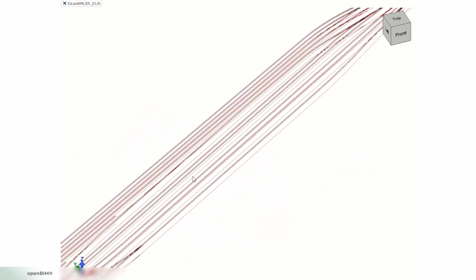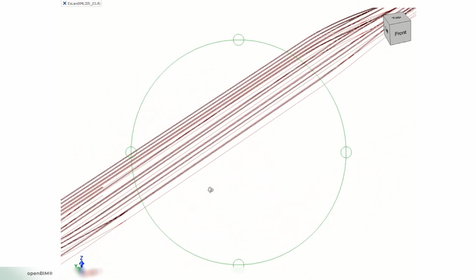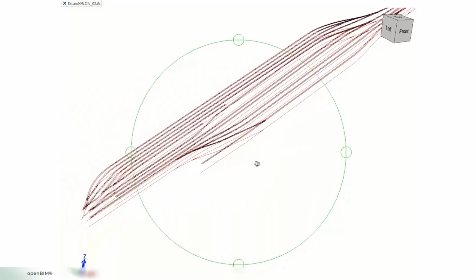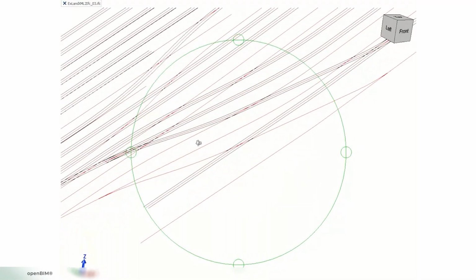And now, let's look at a short demonstration of IFC 4x3 geometrical abilities in OpenIFC Viewer using one of these files. An alignment can contain different types of segments, which describe configuration for lower parts independently from each other and construct the resultant alignment curve on the final stage of visualization. Each segment trims an underlying base curve that uses simple primitives such as IfcLine and IfcCircle, or new complex curves such as IfcClothoid or other IfcSpiral subtypes.